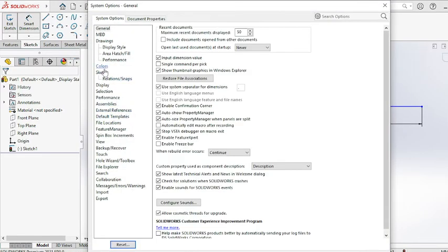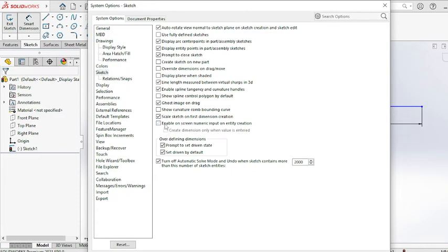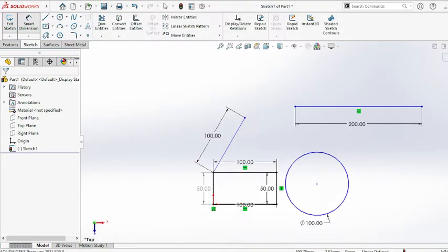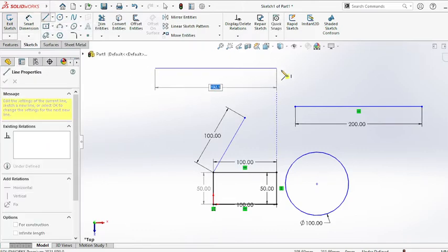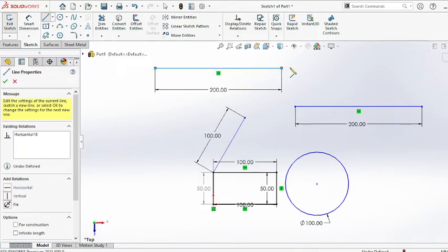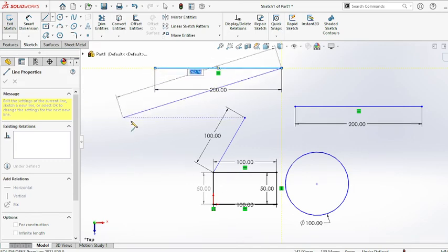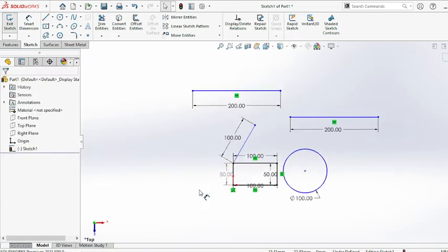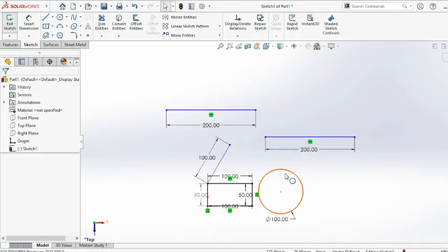See, click on the sketch options. So enable this command option, I want to switch on both of these. Click on OK. Okay, you can press enter. See, now you can go here, line command. You can see, observe this. Length is visible now. 200 I need, 200, enter. Directly you can draw a 200 distance. Okay, so in this way you can apply the smart dimensions. You can apply dimensions to your figures.